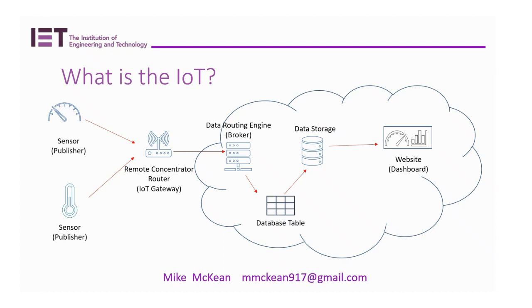And typically you want to update the data infrequently. So it might be in what's called smart agriculture, where it's what's happening in terms of temperature or water or humidity somewhere, and you're sending data back to the concentrator maybe twice a day, and that's sent to the back end. Right, so that's LoRa. That's the LoRa transceiver that sends and receives data, and these are the remote sensors in a normal way, and that would be your back-end application.